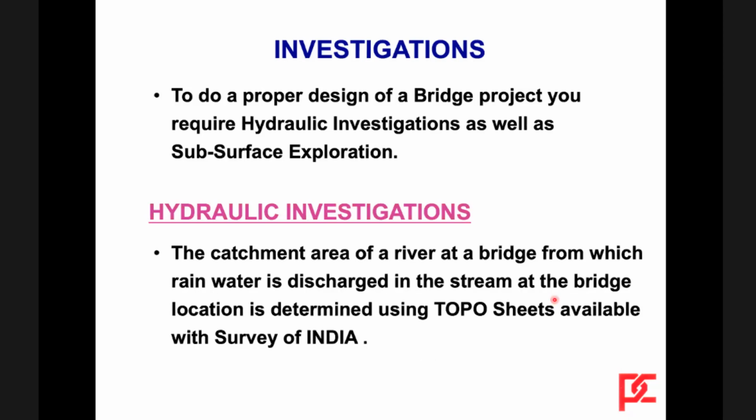Then for the proper design of foundations, investigations are required, both hydraulic investigations as well as soil investigations. In hydraulic investigations, the catchment area of a river at a bridge, from which rainwater is discharged into the stream at the bridge location, is determined using topo sheets available with Survey of India.